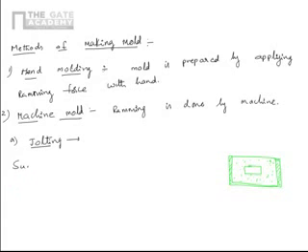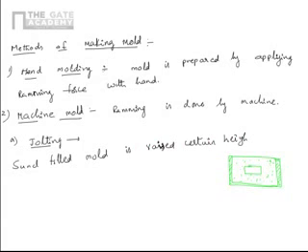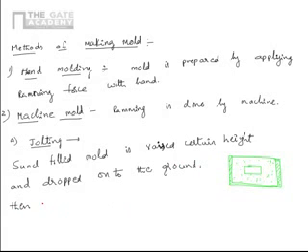The sand filled mold is raised to a certain height and dropped from there, dropped onto the ground. Then the ramming action takes place.